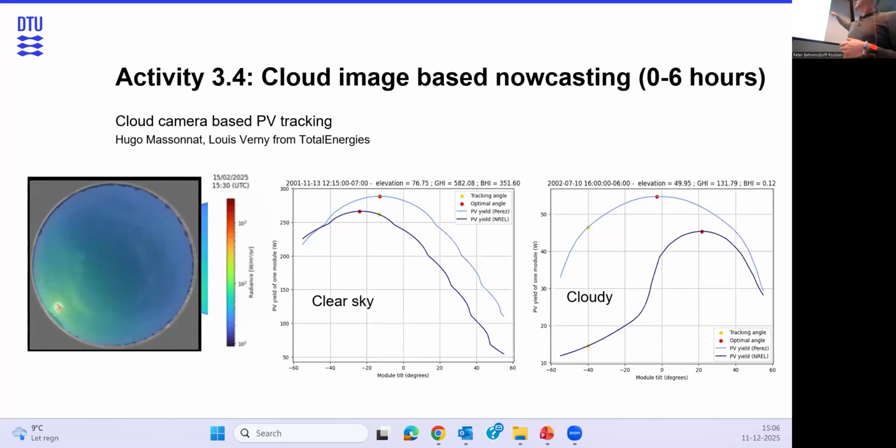And on a cloudy day, there's actually a significant difference, where the research showed that not being horizontal during cloudy periods can sometimes yield more energy because the radiant distribution across the hemisphere is not 100% uniform, even though it would look like that on a day like today.